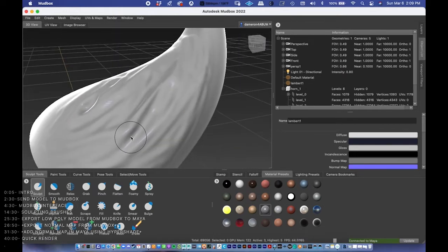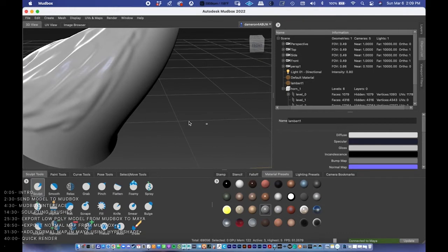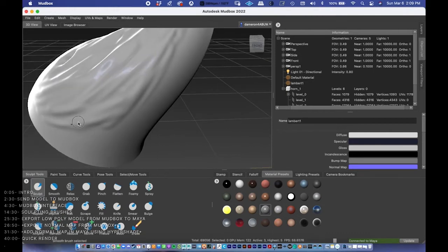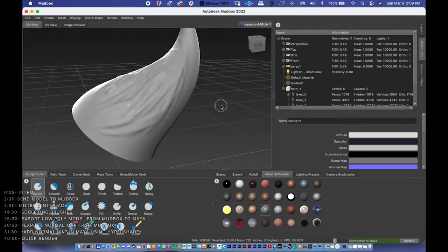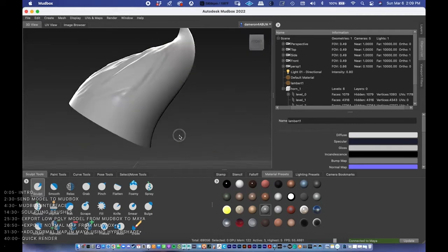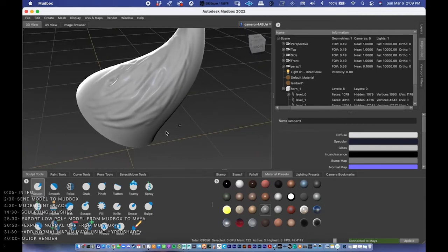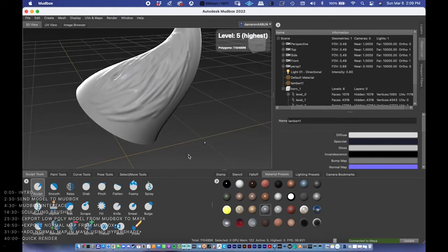That's bad. But if I hold shift and I do smooth, you can see that we're getting a lot more traction with it. So if things are looking a little too lumpy and you need to smooth them out, you might need to just take your subdivision level and move it down for a minute. I'm just going to press function and then up a couple of times and bring it back to its highest here. So that's the sculpt tool and the smooth tool right there.